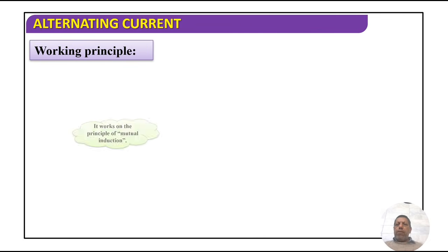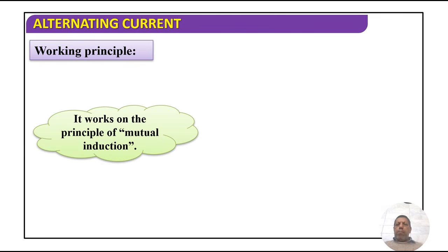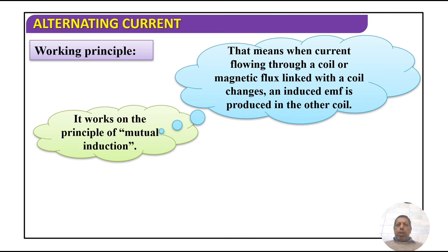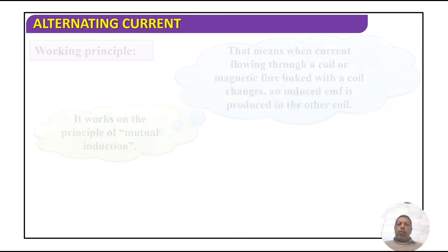Then working principle. It works on the principle of mutual induction. That means when current flowing through a coil or magnetic flux linked with a coil changes, an induced EMF is produced in the other coil.